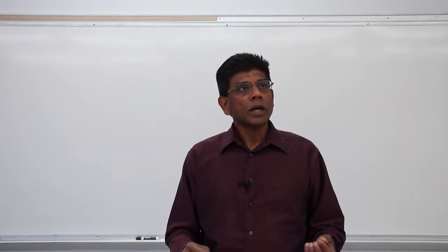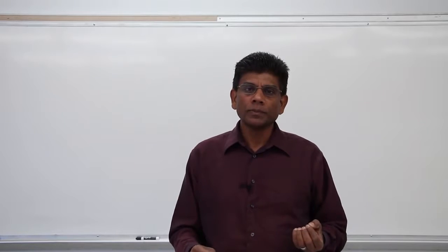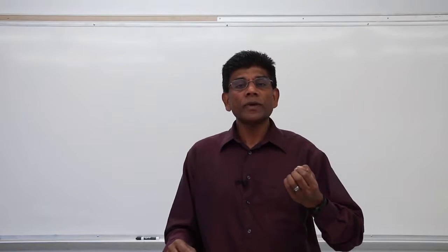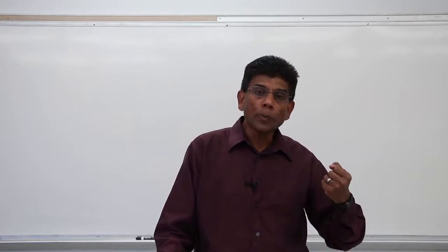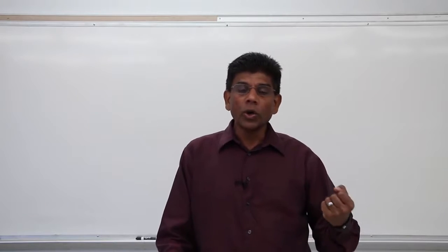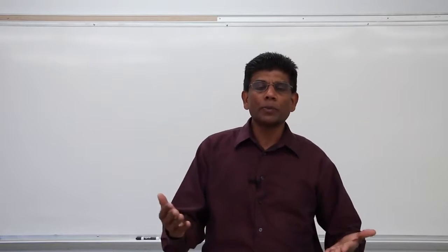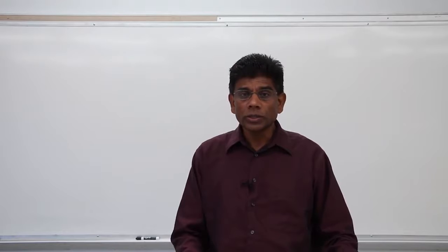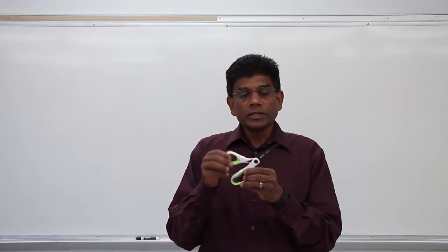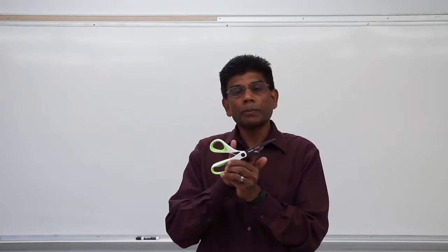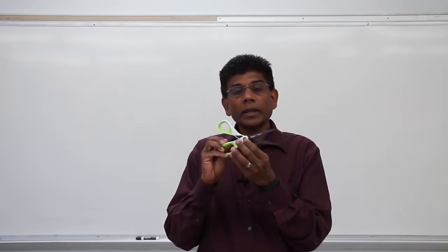Think about a pin joint or a pin support. Well, you see this in your life every day. Every time you open a door or close a door, you are actually using pins. The doors are typically supported by hinges, which are actually pin supports. Not just the doors. Take a scissor like this. The scissor has actually 3 parts, the upper part, the lower part, and the pin connecting them. So these two parts are connected by a pin support.